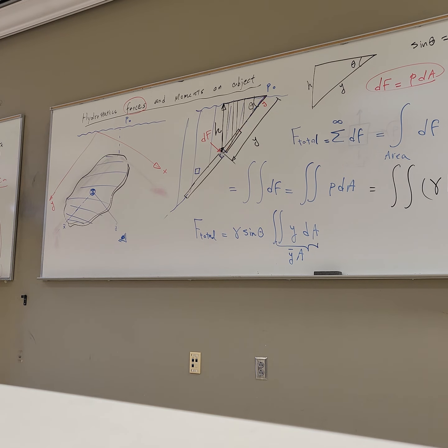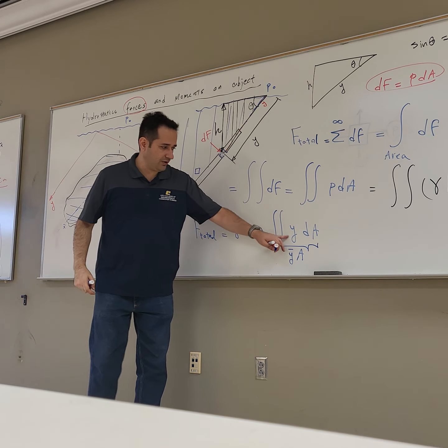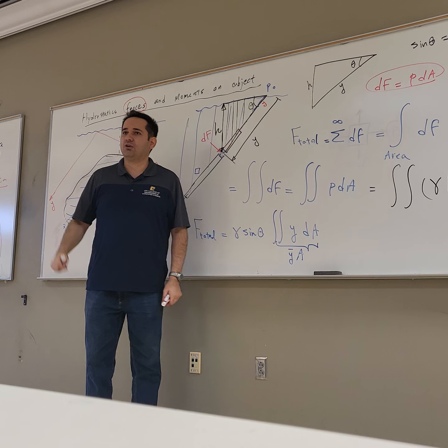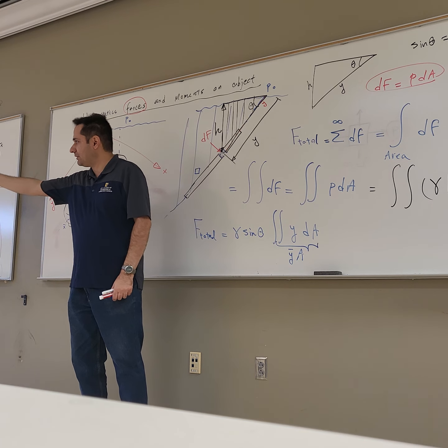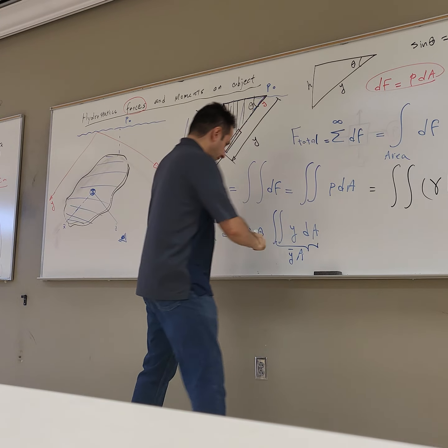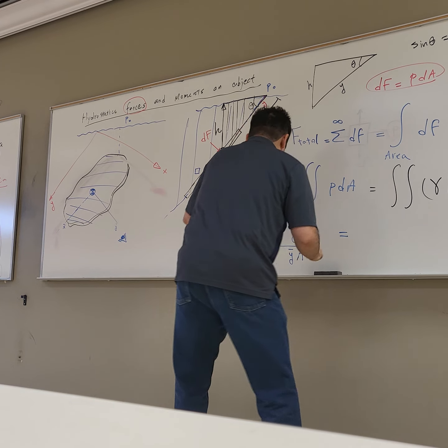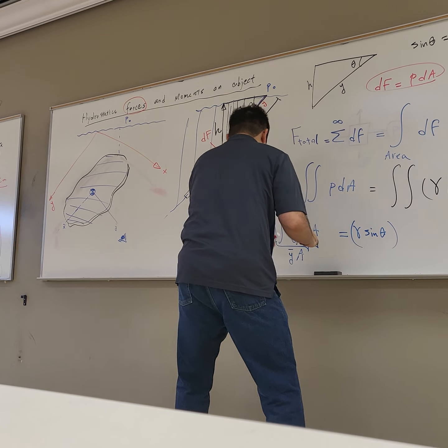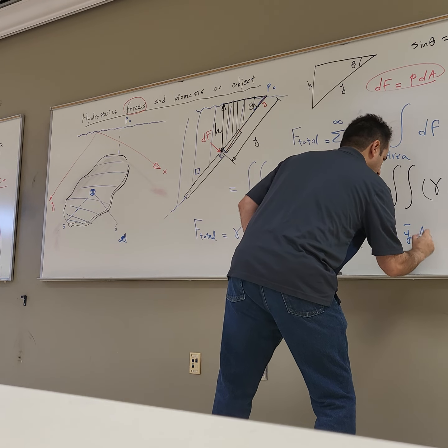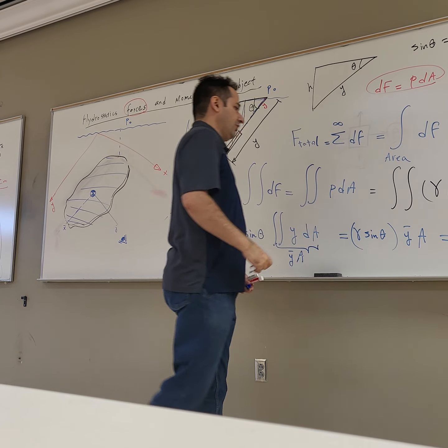So we try to convert the double integral into the centroid. That's the reason I put y bar times A, because I can get the centroid from the handbook. Instead of doing a double integral, I can go to the handbook and get the centroid. So for that, I write what? Gamma sine theta times y bar times A is equal to...